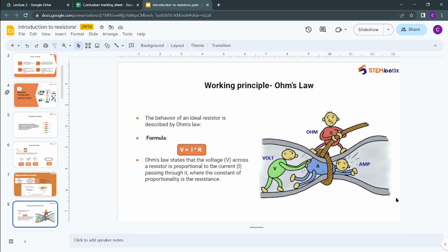As I said earlier, in series connection the resistors share only one common node. As you can see from this diagram, the current enters through this node and has only one path to flow through, which means the current flowing through each resistor is the same for the whole network.